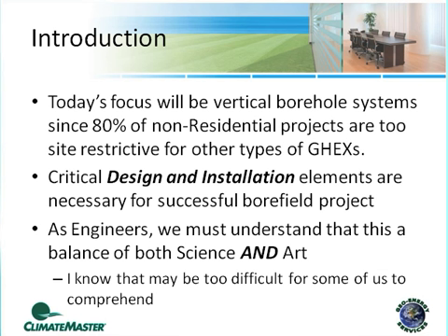I'd like to start off with a brief introduction of ground source heat pump systems. The first thing to note is the topic and discussion is going to focus mostly on vertical borehole systems, mostly because 80% of the projects that are out there in the commercial market represent vertical borehole systems. Certainly there are horizontal systems and pond and lake loop systems, and if we have time here at the end, I will cover briefly a couple of things on those. But otherwise, we're going to stick mostly to vertical borehole systems with regards to the outside part of the projects. It's important to note that there are other design and installation elements that we want to be aware of, and I'm going to cover those as well.